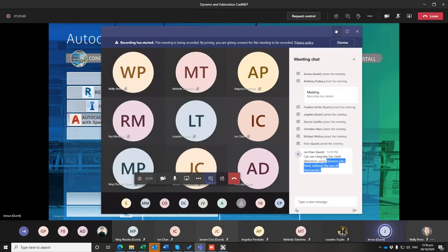The important thing here is the report, where it can map out the location of the clashes. Since Navisworks can map out the XYZ and grid location of the clash, it was easier for Dynamo to lay out those clash indicators that we have. But it is possible that you can only use Revit. But again, if you use Revit, you won't be able to map out the clearances. So it is possible, yes.